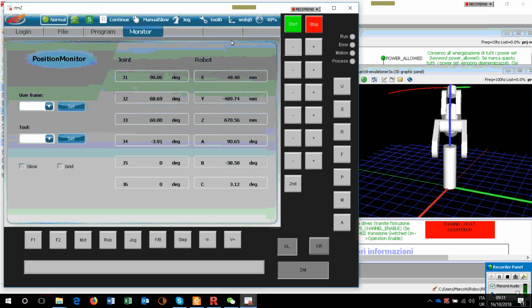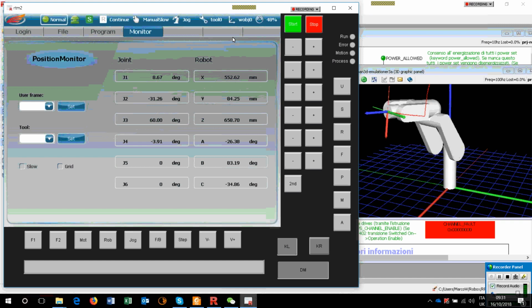Now I make it, just to give me a little time, I want to bring the robot to 0, so almost like this. So J1 you see is this joint, okay, moving this way. J2 is this one, the second, so that joint here. Now I make something more clever. J3 is this one. Now I turn the robot. So you see, J2 is almost here, close to the base.